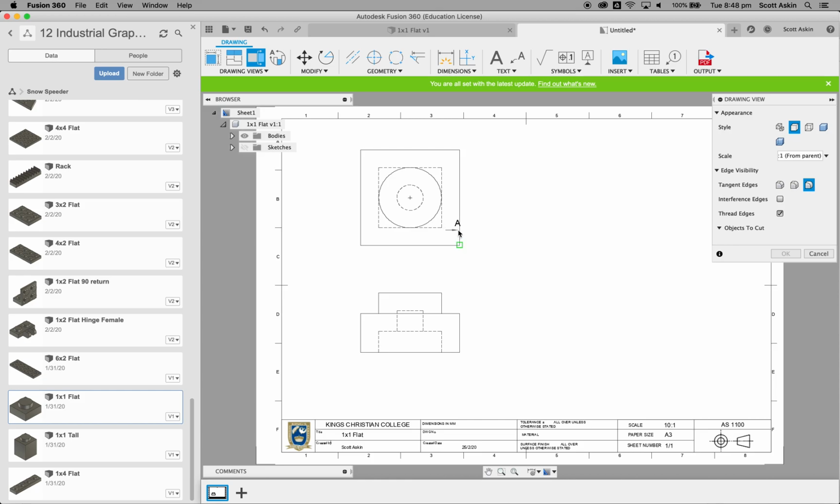And what I want to do here is draw an upside down back to front L in this position here, which will determine our sectioning plane position. So what I've done there, I've just hovered along the outside edge there until that triangle appeared. And triangle means halfway. So once it's hovered there, let's move my cursor slightly to the right so the A is slightly outside the drawing.